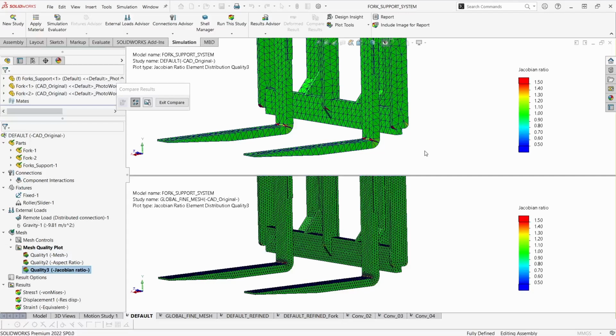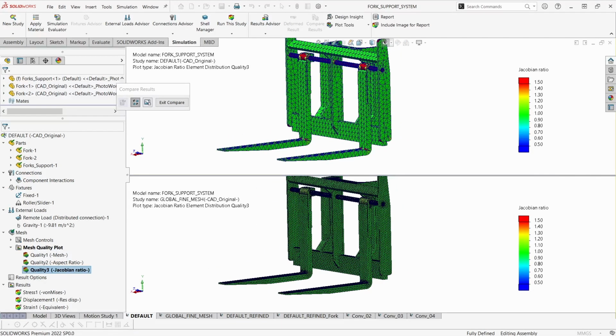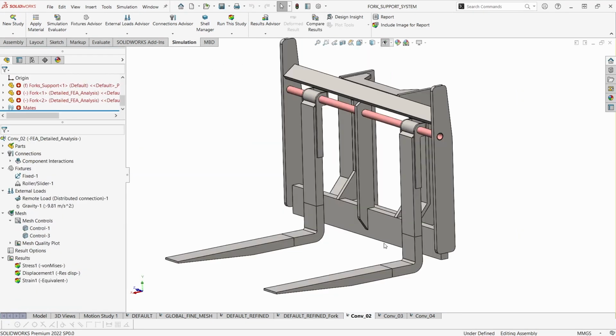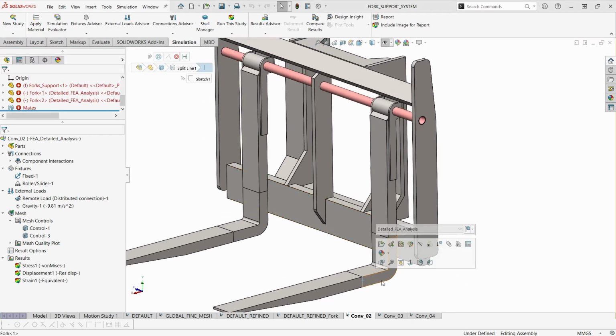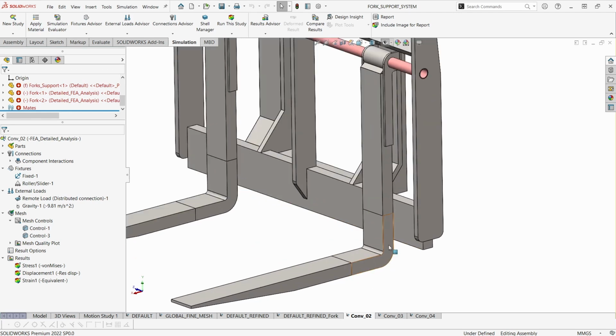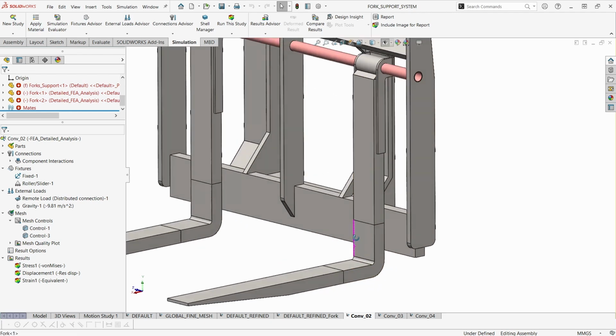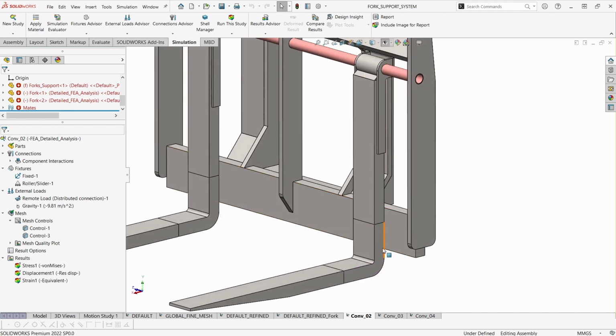Let's continue. Okay, to show you the mesh convergence analysis, we are going to use the last model that we obtained in the previous video, where we just refined partially the component. This will allow us to move faster when refining our mesh. Okay, here we have it. You can see where I prepared these cuts here and here, far away from the corner, so we have enough distance to do the mesh transition far away from the zone under study, but avoiding refining the complete component.